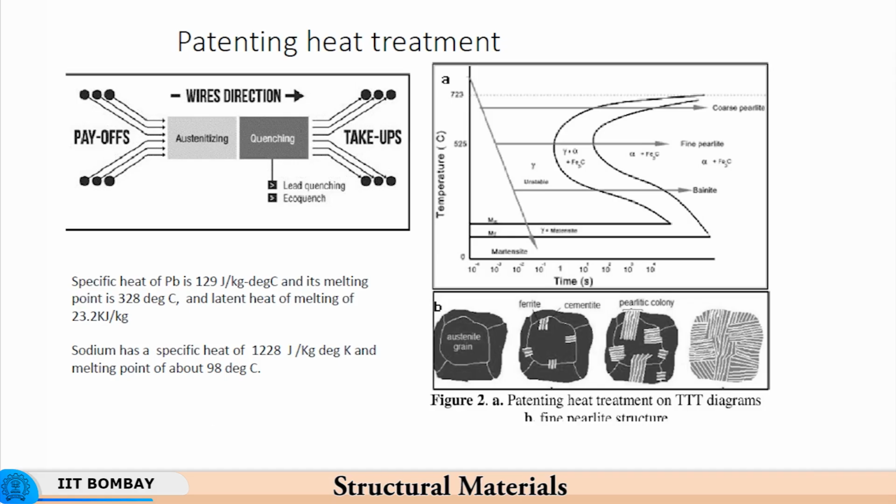is expected, again these properties or this structure cannot be achieved purely by heat treatment, it needs the chemical composition to be of that specific type, meaning the carbon percentage should be 0.8%, and exactly at 0.8% the eutectoid transformation takes place, and after that you have the entire thickness of the rope or entire thickness of the wire being in a pearlitic state. So, it has got very high strength. Even if it deforms plastically, the strain hardening rate is very high.